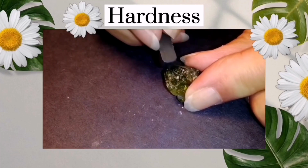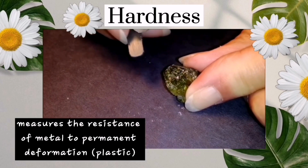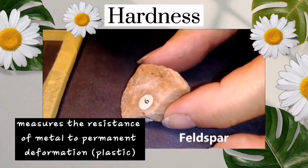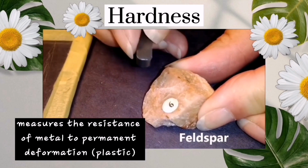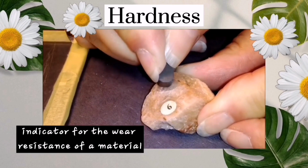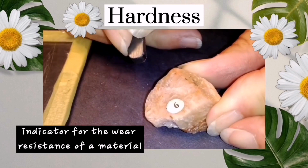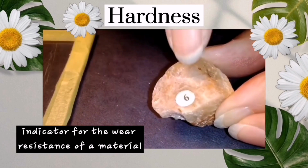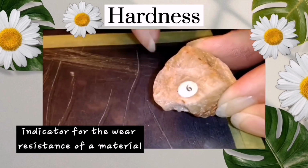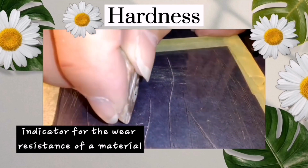Hardness is one of the mechanical properties, which measures the resistance of a metal to permanent or plastic deformation, indentation, or scratching. Furthermore, hardness can be an indicator of the wear resistance of a material, and the term wear resistance refers to the material's ability to resist material loss by some mechanical action. Therefore, the harder the material is, the greater the wear resistance will be.